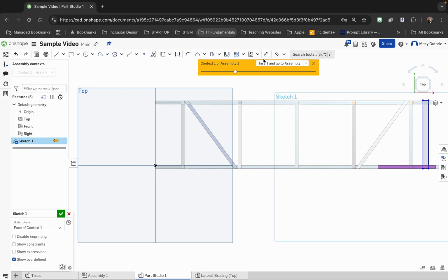And I'm going to dimension this balsa stick before I do anything else. It is 1/8 inch, always 1/8. And if this happens, don't stress it. It's just because when you made it smaller, it reduces it like in a scale all the way around, so it reduced the other side too. So if you remember, you place these two, however far you placed them apart. I was 2.5, and I need to add the 1/8, so it will go all the way across, and I do want to put that in parentheses. And now you will see it goes all the way from one end across the other.